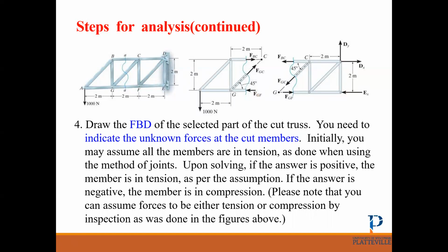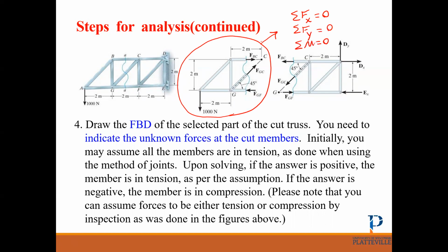So at this point, we pick the section we want to analyze, and then we can apply the equilibrium equations: sum of Fx equals 0, sum of Fy equals 0, and sum of moments equals 0.